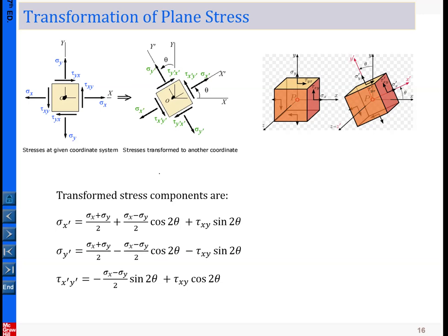In terms of the three-dimensional view, you should be able to see it like this. Again, you are the little person, looking in this direction in front of you, and what is projected to you is the two-dimensional view, something like this one, okay? And this is a general three-dimensional plotting of the plane stress, but again, two-dimensional graphics should be sufficient. So again, this is a repeat of the transformed stress element equations for you to pick up.